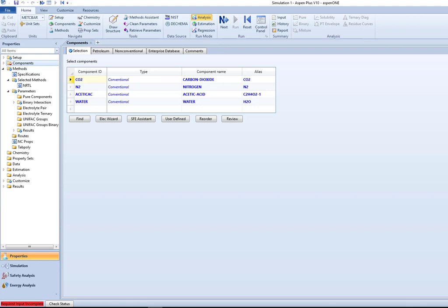If you want to look at using a column for a scrubber and one that was being used for distillation, they really would look pretty much the same. In fact, visibly the only difference to the column itself would simply be that in a scrubber you always have two different feed streams, one at the top and one at the bottom. And in a distillation tower you could have any number of streams and they could come in at any point in the tower. The real primary difference is going to be in the peripheral equipment.